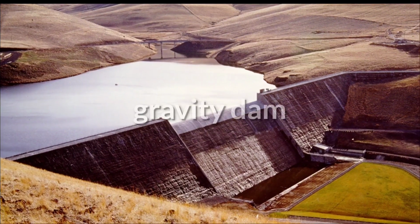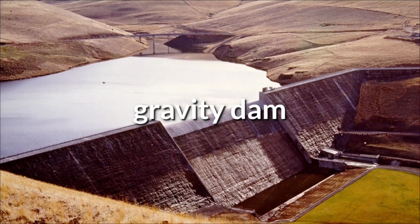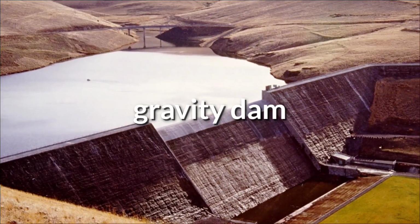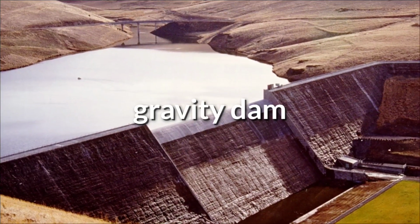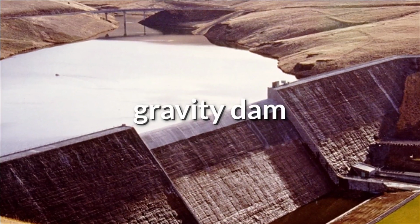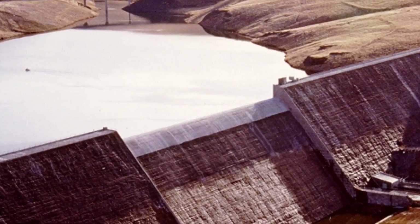Here I want to explain what uplift is. Uplift is the vertical force exerted by the seepage of water which passes below the dam and penetrates the cracks in the body of the dam. Usually cracks develop because of this uplift pressure. So prevention of uplift pressure is most important in gravity dams.